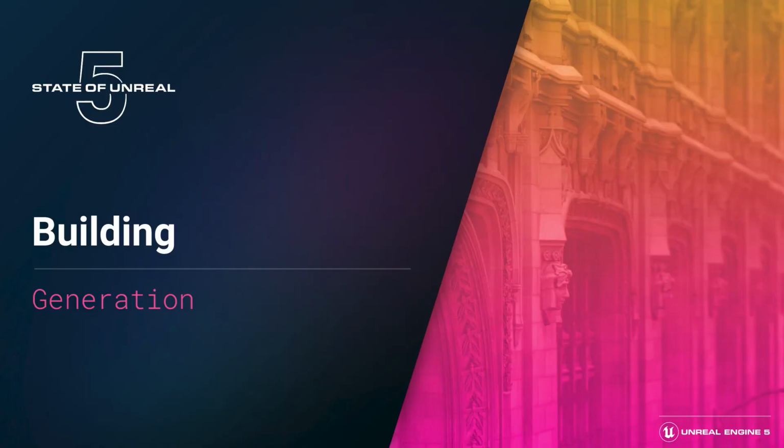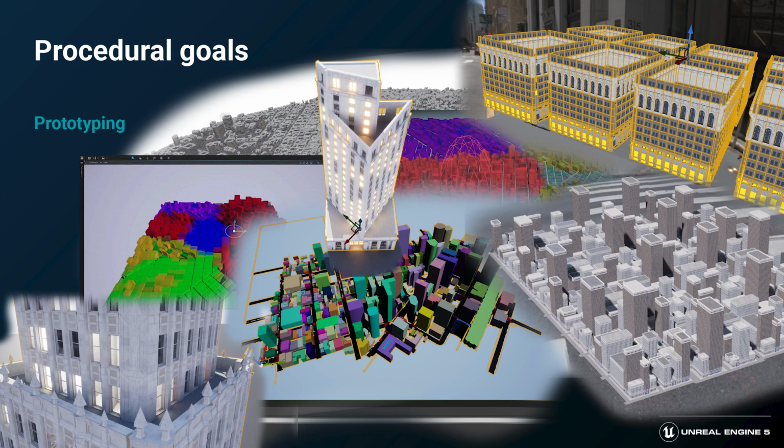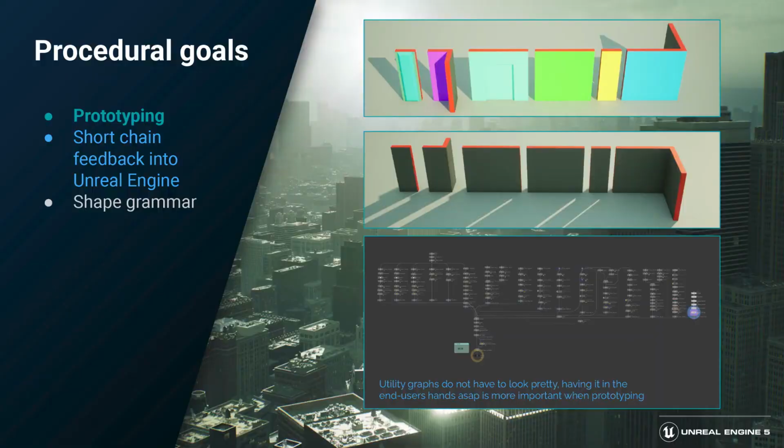Let's talk about the procedural building generation in the Matrix Awakens demo. In the prototyping phase, we wanted to keep workflows as simple as possible, one DCC straight into the Unreal Engine. Houdini and Houdini Engine are obvious choices for prototyping procedural ideas and workflows. Iteration speed is king when you want to evaluate concepts. We did a lot of prototyping and iterating. A great example of this ethos is the building module template generator, quickly allowing building module proxies to be created on demand to specific sizes.